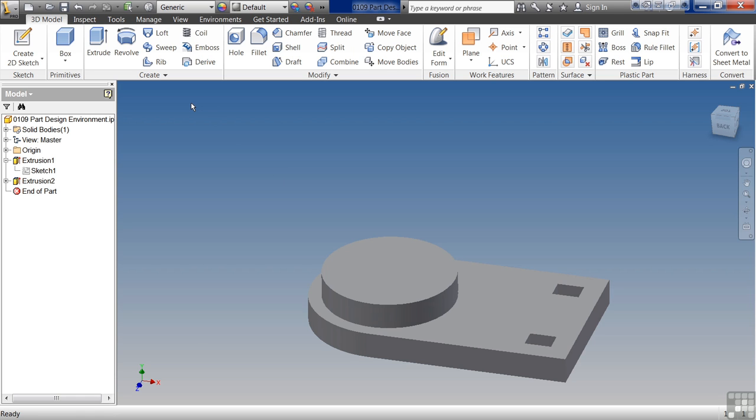part modeling environment. If there's something that you need to do to a part, Inventor's smart enough to give you those options. If the options are not available to you in the screen you're in, there's a good chance that you need to change the environment. Meaning if you are in an assembly and you're trying to extrude something, that can work, but it may not necessarily be the right environment to do it. You'll notice that the fillets aren't there and things like that. So make sure you're conscious of what environment you're in to be able to modify things.